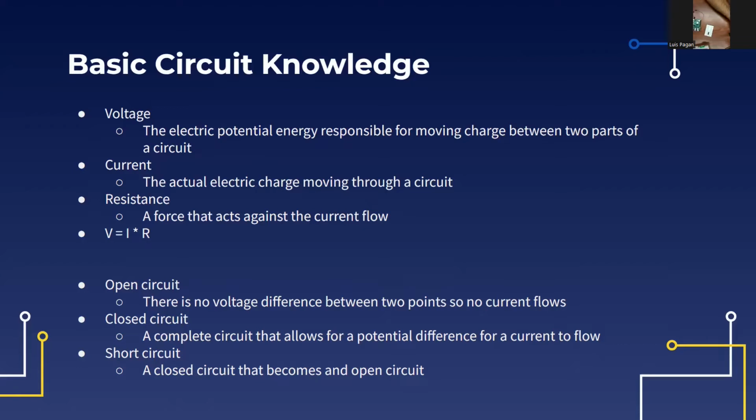So you would just want to be careful with this when you're wiring up stuff to the Raspberry Pi and the, I guess, H bridge, because the terminals on the Raspberry Pi have limits. You have to make sure you're not applying, let's say, 18 volts. Let's say you had 2 9-volts in series.